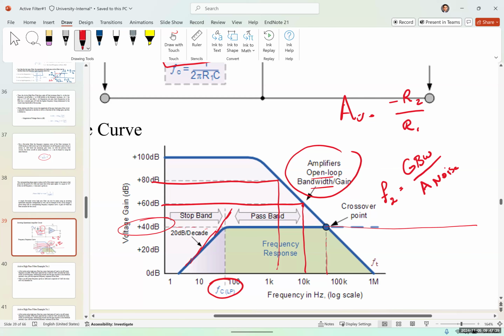So at this point, it's just going to directly come back. So you're not going to have a very good frequency response. If you have 80 dB gain, for example, your frequency response would look like this, which would be a very, very limited frequency response. So the lower the gain is, the wider the frequency response. The higher the gain, the narrower the frequency response.